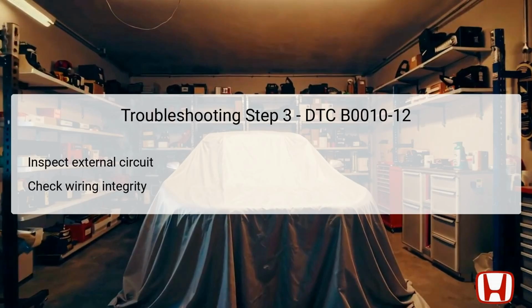Use the appropriate diagnostic tools to verify that these wires are not shorted to power. The integrity of these wires is paramount. Any faults found at this stage can cause irregular power flow, leading to the fault code being stored in the SRS unit. Document the results of your inspection carefully, as these findings will guide the next steps in resolving the